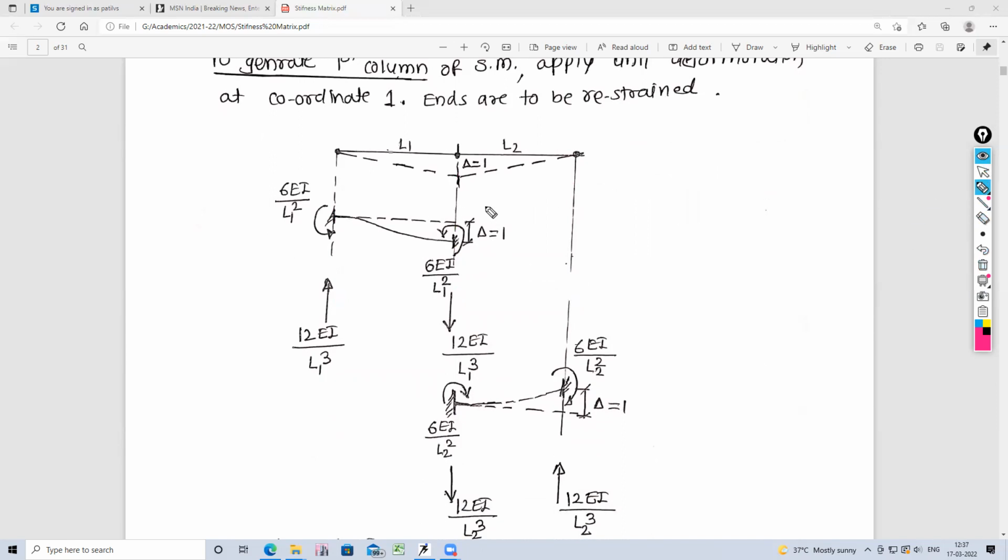That is shown separately in the first part and second part here. So this is the first part, where the unit deformation is applied at this particular end, and this is at the same level. So this becomes a level difference. It is called the sinking of the support. So the end which is at a lower level, at that place a sagging moment will be there.